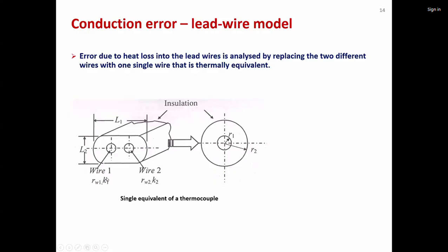And the outer covering, instead of using these flat sides L1 and then a rounded side L2, you just construct one circular cross-section R2. So basically this wire has a radius of R1, and the annular region R2 minus R1 is the plastic, the polymer. The R2 minus R1 region is for insulation, and R1 is for heat conduction.